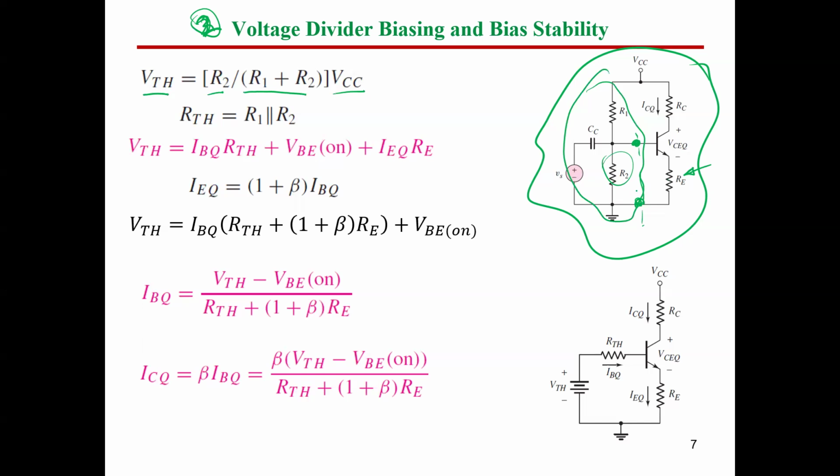Okay. And what is the Thevenin resistance for this circuit? Applying superposition again means the AC will be removed, and you know that when we get R Thevenin we delete every voltage source in the circuit. If this is my circuit here, we have two resistors like that. These are the two terminals that we need to get R in between. You have here VCC, this is R1, this is R2.